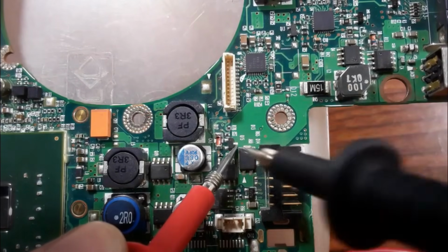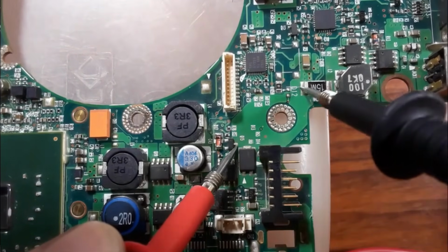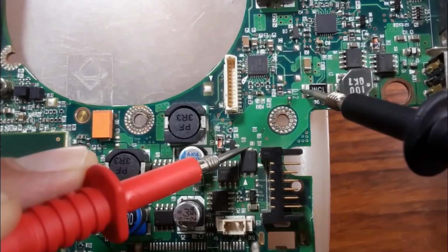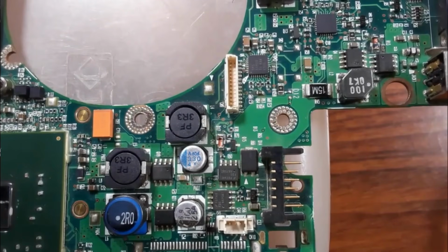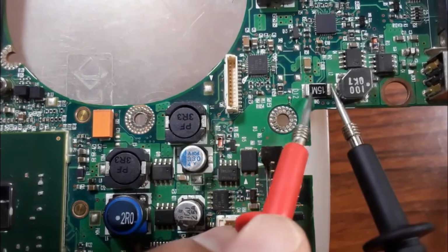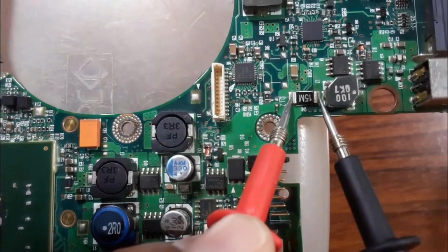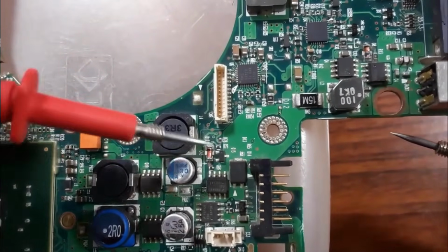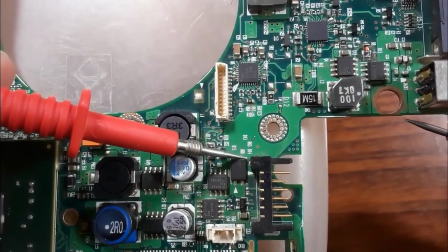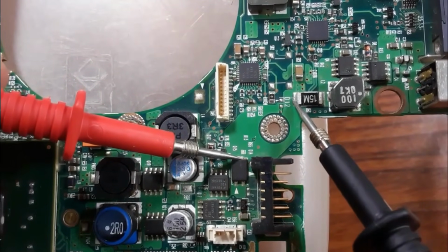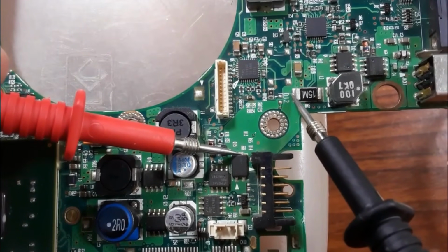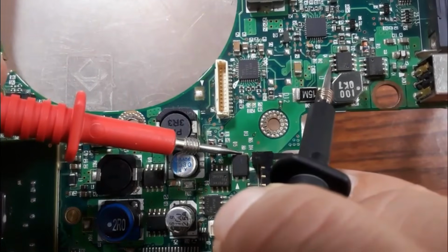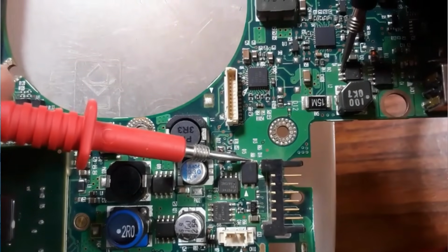Do you see? Also here. Do you see? Also this diode is connected to this resistor. Okay? And of course, because this is a current sense resistor, it is like a fuse. If we put the probe here in this diode, and go, as you see, it is connected to this and also to this coil, and of course to the MOSFET, as you can see.